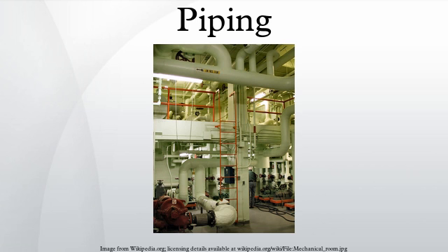Wooden pipes were easier to maintain than metal, because the wood did not expand or contract with temperature changes as much as metal, and so consequently expansion joints and bends were not required. The thickness of wood afforded some insulating properties to the pipes which helped prevent freezing as compared to metal pipes. Wood used for water pipes also does not rot very easily. Electrolysis, that bugbear of many iron pipe systems, doesn't affect wood pipes at all, since wood is a much better electrical insulator. In the western United States where redwood was used for pipe construction, it was found that redwood had peculiar properties that protected it from weathering, acids, insects, and fungus growths. Redwood pipes stayed smooth and clean indefinitely, while iron pipe by comparison would rapidly begin to scale and corrode and could eventually plug itself up with the corrosion.